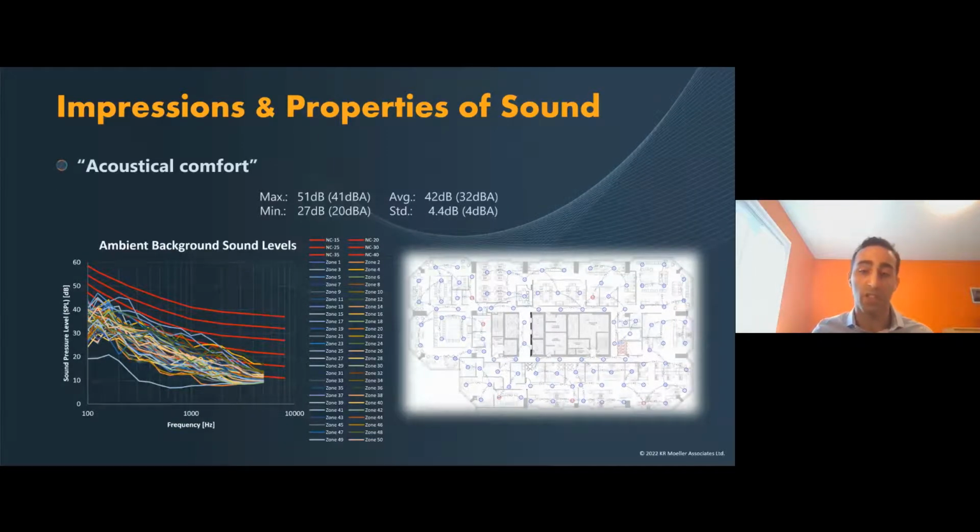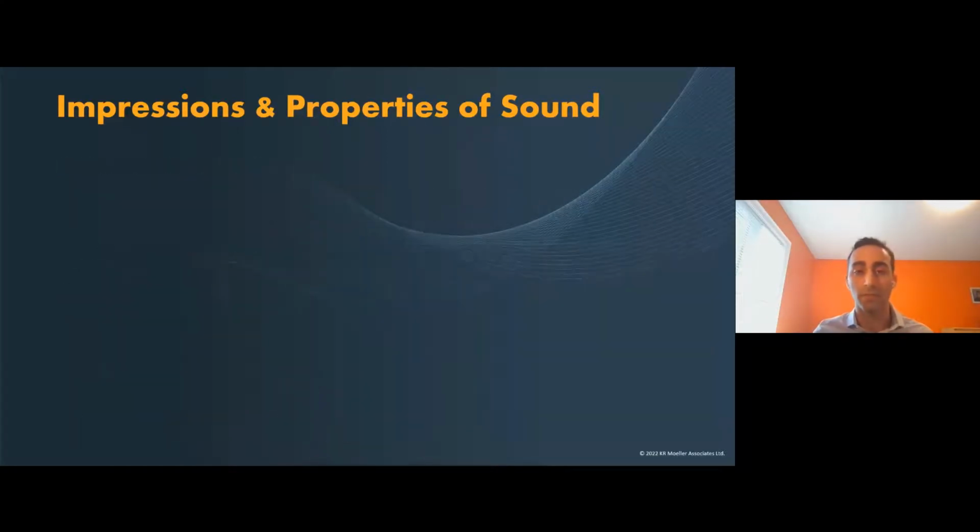Some of you may suggest that the variations in level would never be acceptable in a project. However, the majority of these background noise measurements comply with the second most stringent requirement in Table 1 of ASHRAE's handbook, NC 25. This outcome is possible because these tables are maximum allowances for noise, not the actual acoustic conditions.